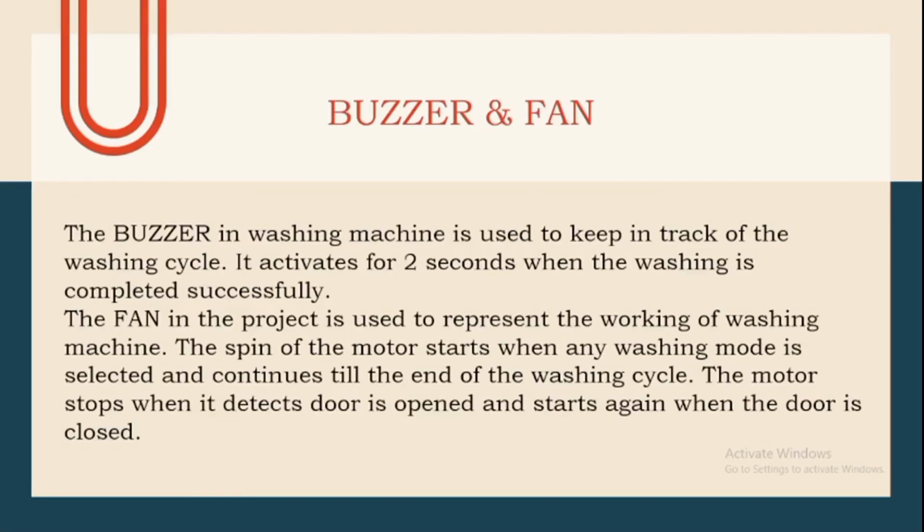And the next slide was buzzer and fan. The buzzer gives audio feedback used to alert the user at the end of the washing cycle. It beeps for 2 seconds after completion. The fan acts as the washing machine's motor. When any mode is selected, the fan spins. If the door opening is detected, the fan stops and resumes when the door is closed. This simulates real-time motor control logic.